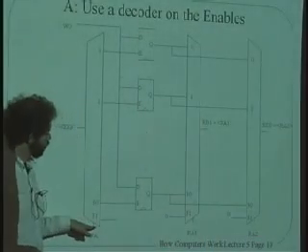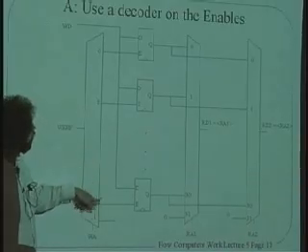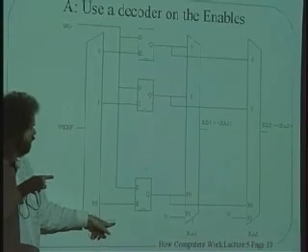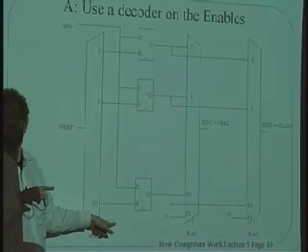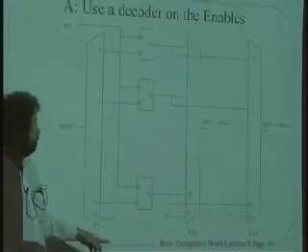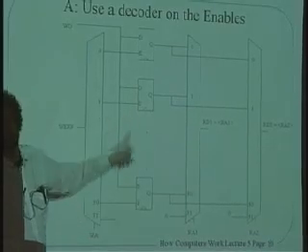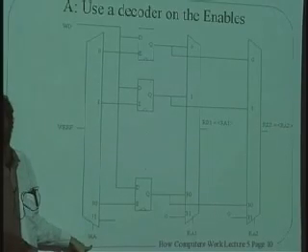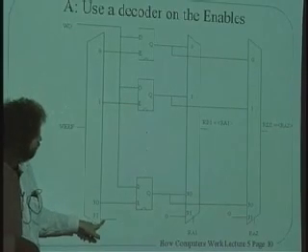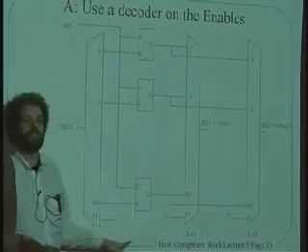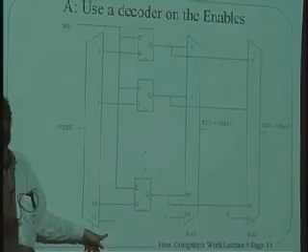Hey, look at what happened to register number 31. If we choose to write register 31, all the rest of them are going to be 0. And register 31, this little wire is going to come out here and say, poor, pitiful me, no one's listening to me. And why is that? Because the bits that come in here on WD just go nowhere. And so none of the registers is going to be turned on if we choose register 31 as the write address destination for where we're trying to write. And that's how we implement in this very trivial way, making register 31 equal to 0 on read and ignored on write. That's all there is to it.